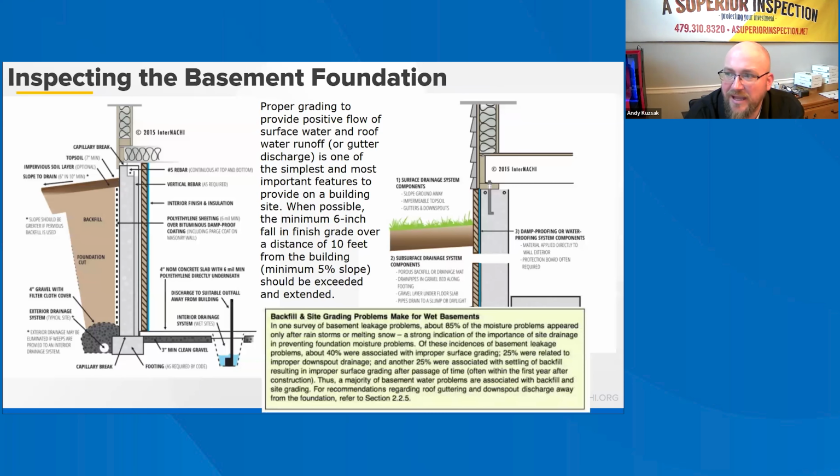Damp proofing involves applying one or more coatings of impervious compounds to prevent water vapor passage through walls under slight pressure. Waterproofing measures are reserved for conditions with high water table or severe soil water conditions. Waterproofing involves applying a more impermeable membrane to the foundation wall and may include damp proofing plus a layer of 6 mil poly on the exterior below grade portions of the basement's foundation walls. Other single ply or built up membranes may also be used. Waterproofing combines sealing materials and impervious coatings to prevent moisture passage in vapor or liquid form under significant hydrostatic pressure.